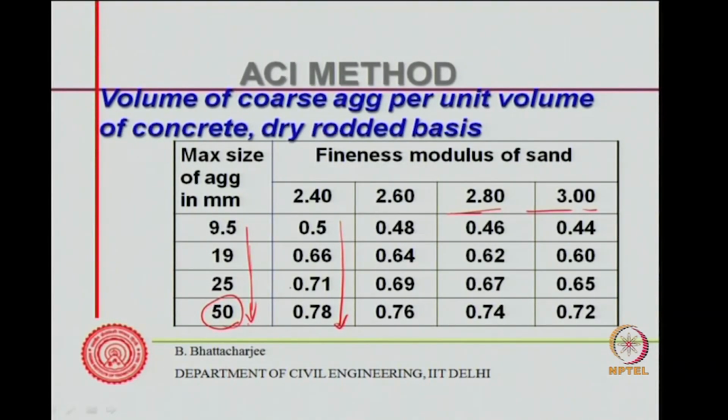As the MSA increases, total aggregate content increases, in other words the sand content would reduce because it will have better packing.